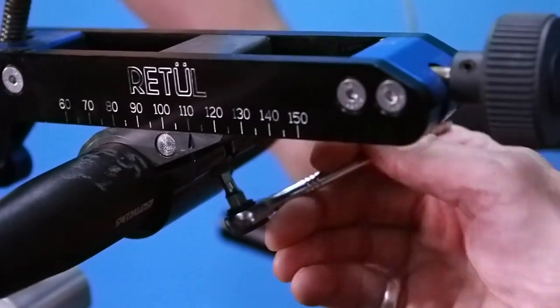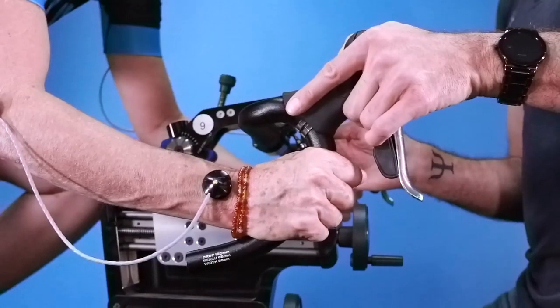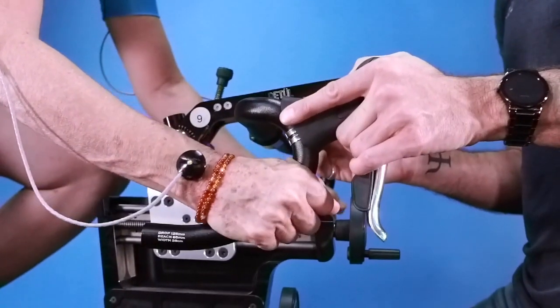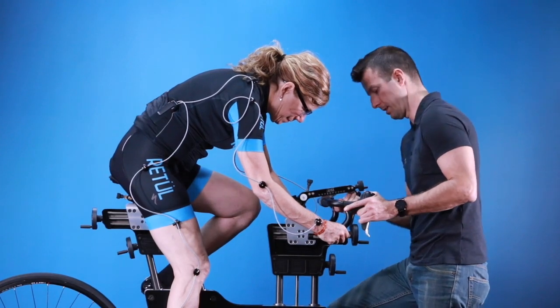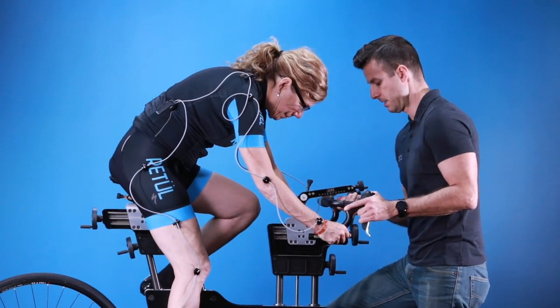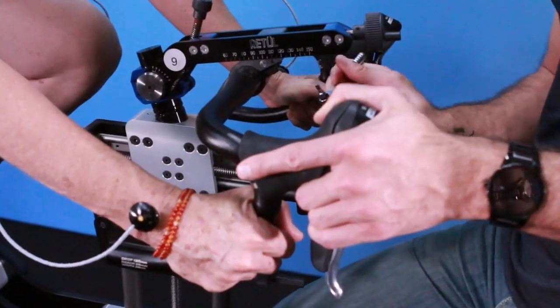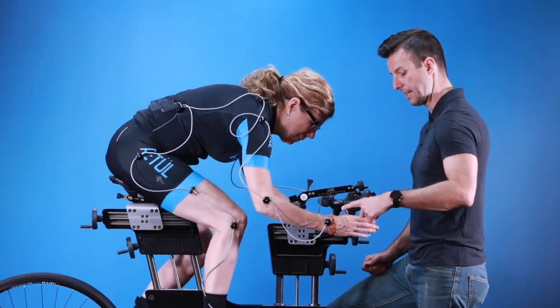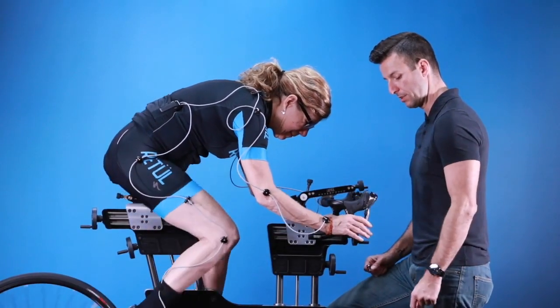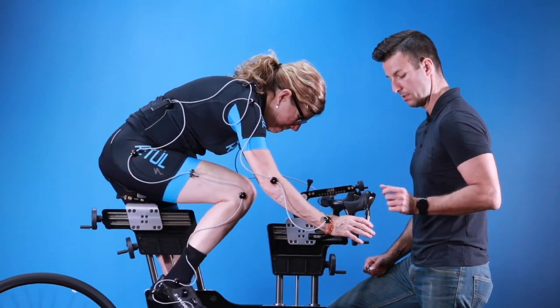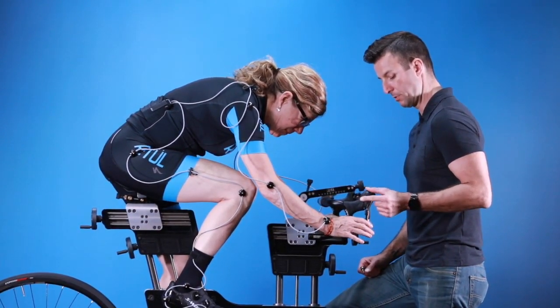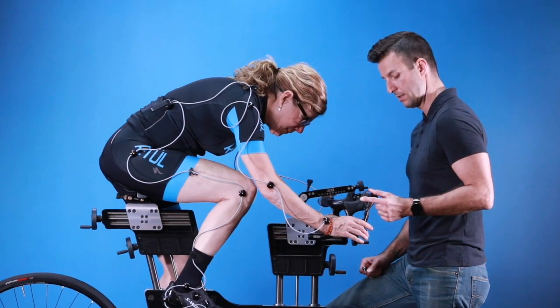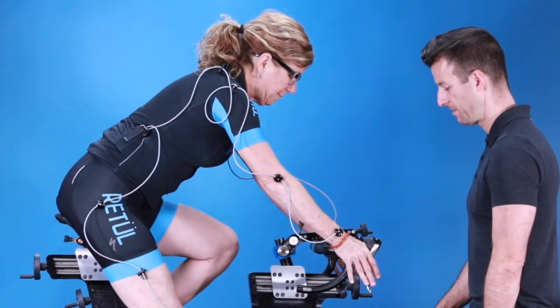The fitter begins by loosening the faceplate, and then instructs the rider to angle the drops into a comfortable position. The fitter can offer some advice here. Once the rider finds a good position, the fitter tightens the faceplate and then asks the rider if she can reach the brake levers. Finally, make an adjustment to the brake lever to bring it in closer if the rider needs a shorter reach. Next, the fitter will assess the rider's wrist position in the hoods.